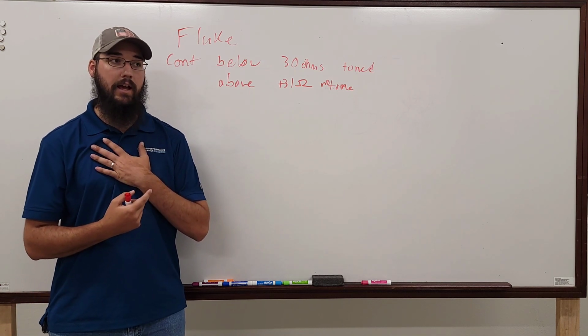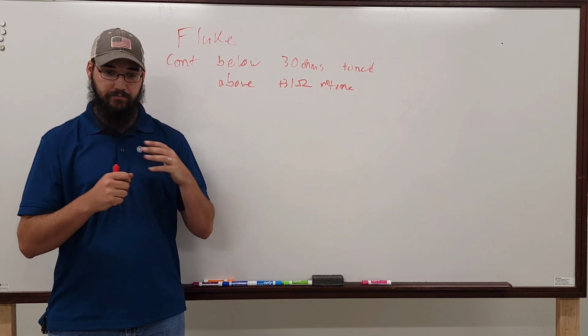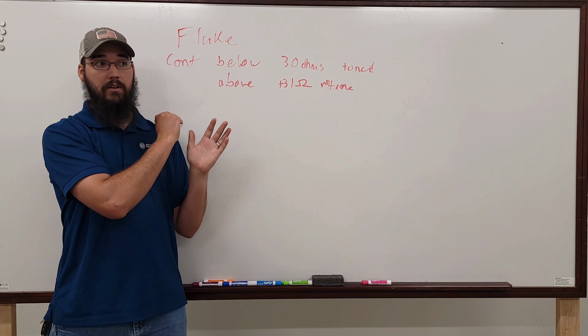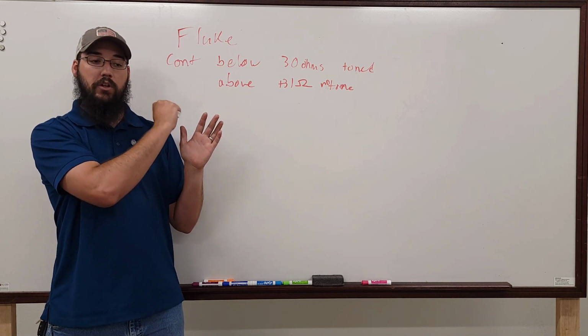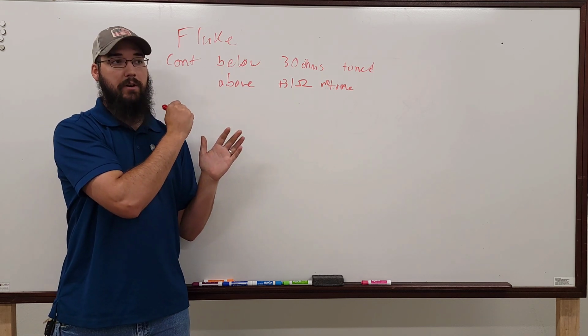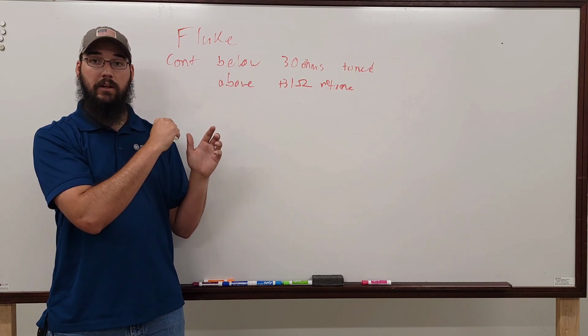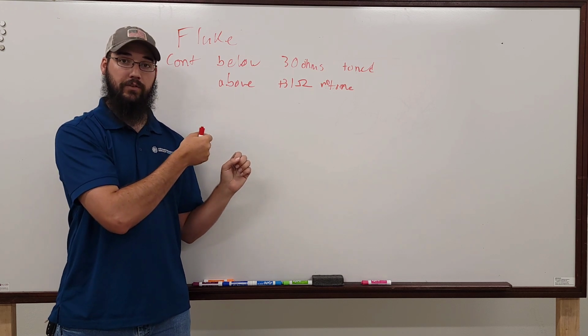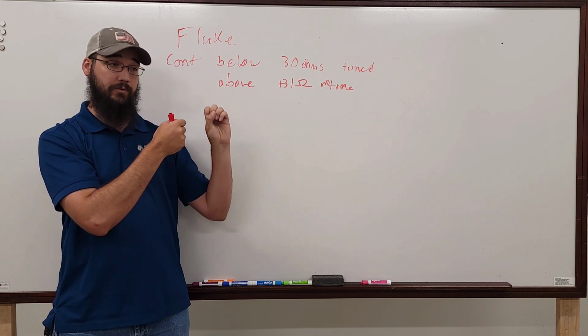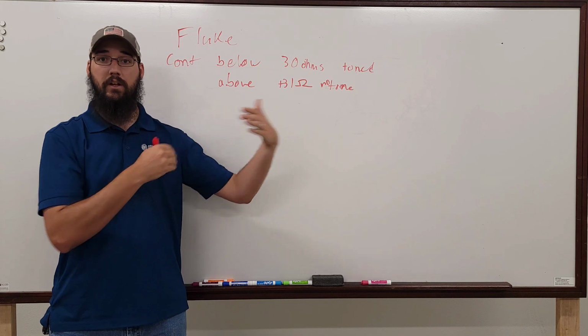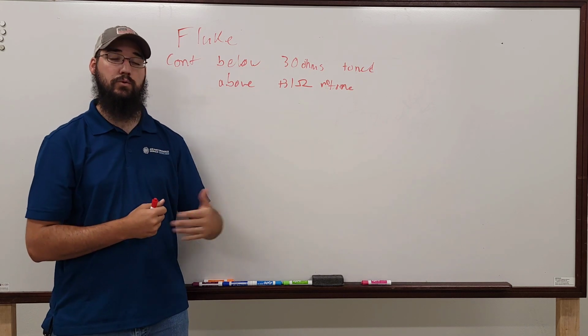It's okay if you want to do it that way. So I have a manual set meter, right? It's okay to start with that, but you have to start at the highest setting and work your way down. So in that particular case, I'm starting at millions of ohms, and if I see 0, I step down to 1,000. If I see 0 at 1,000 ohms, I step to just the hundreds of ohms to get the true reading.